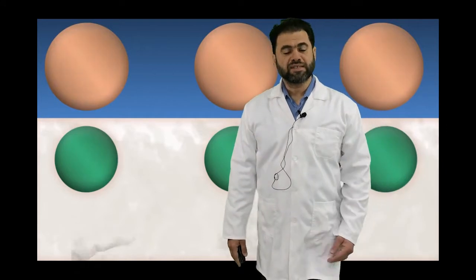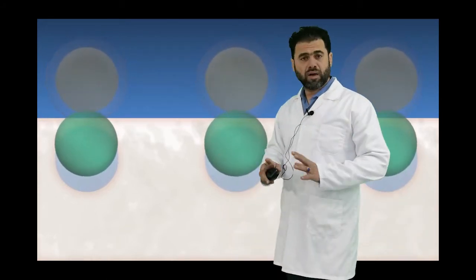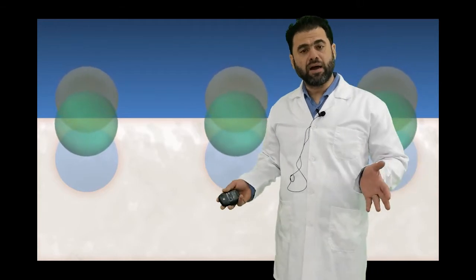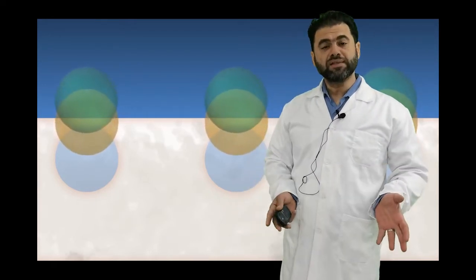Okay, number 4, it's the ion exchange, or we call it also chemical tempering. The surface of the ceramic has sodium ions in its composition. Sodium has a smaller diameter. The potassium has a bigger ionic structure. So potassium is 35% bigger in size with regard to sodium.